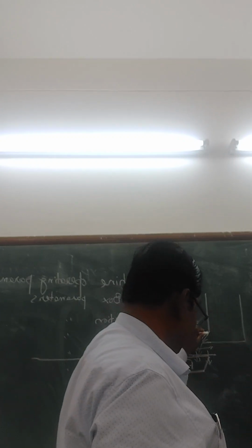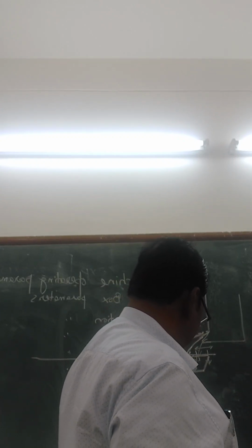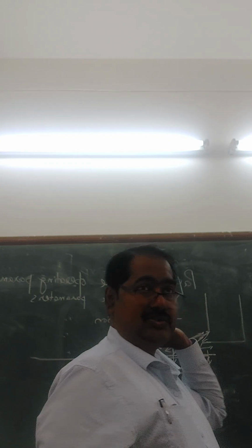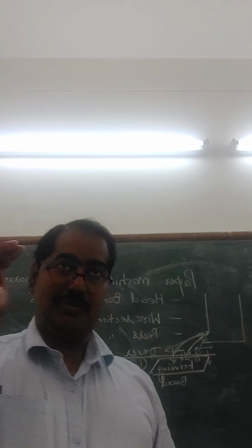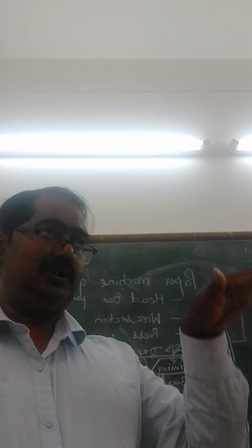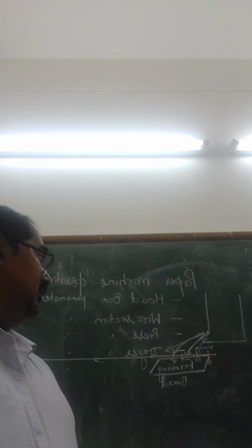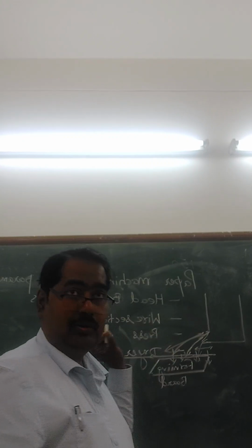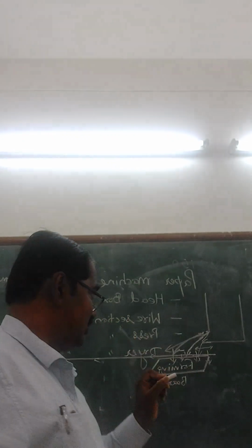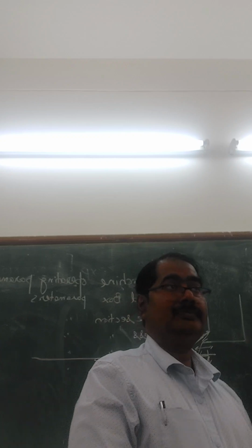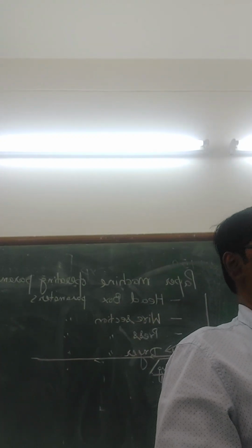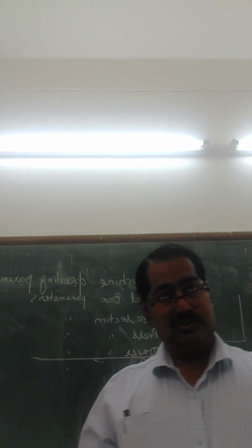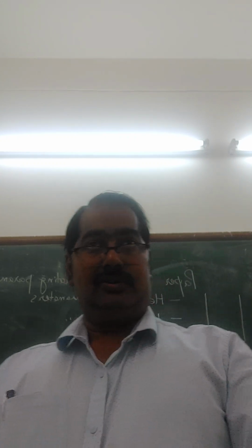And if the jet velocity is parallel, going slightly to farther places, what will be happening? It will have a horizontal component of the velocity. So it will be moving in this direction, so drainage will be slow. So you can adjust the direction of the flow here so that the vertical component and horizontal component of the jet velocity will change.